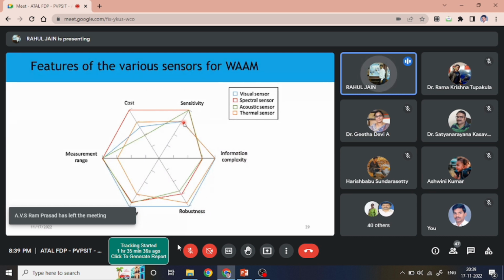And once that has been done, sufficient data needs to be captured. A lot of times, if you are taking one data point per second, the frequency of data capturing should be large enough so that you have sufficient data to process, right? If you are doing one data point per second and the entire process is 10 seconds, you only have 10 data points, and 10 data points cannot give you the required information, right? So you need to get more information, at least 10 hertz or 20 hertz, right? 0.1 second per data point, something like that. At least that level of sampling rate. Once you have that level of sampling rate, you'll have more data which you can process.